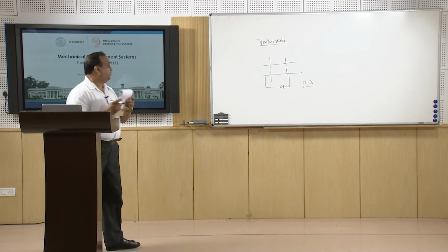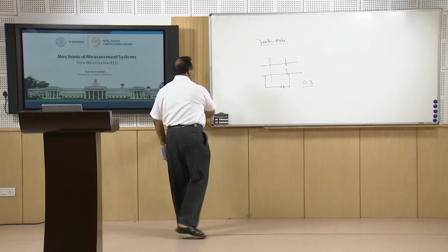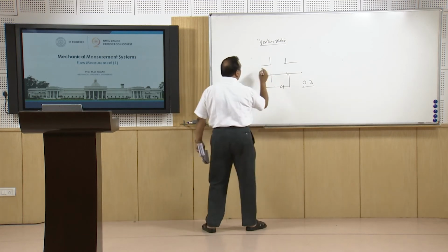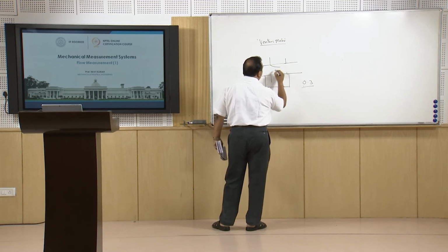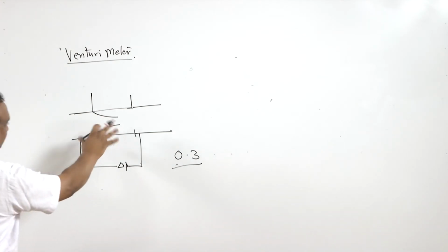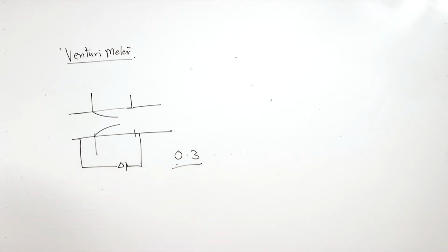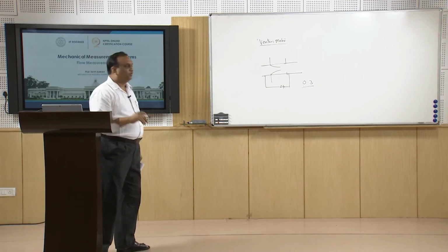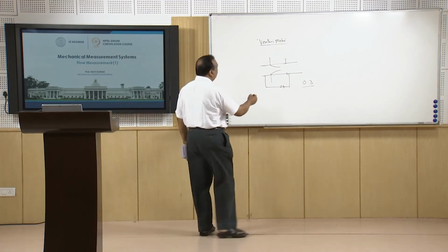There is another instrument which is known as the sonic nozzle. In the sonic nozzle, in the tube there is a nozzle. The rest of the theory is the same. A nozzle is fitted and then again there is pressure loss and difference in head, but the sonic nozzle is a compromise between the venturimeter and the orifice meter, and the sonic nozzle is normally used for gas flow.